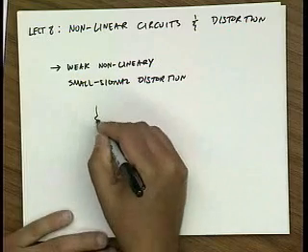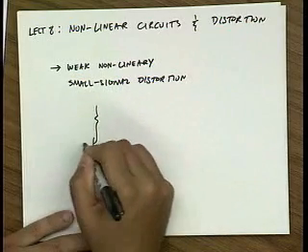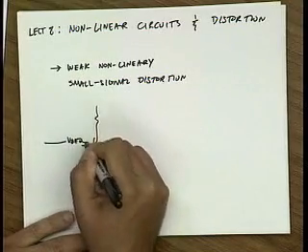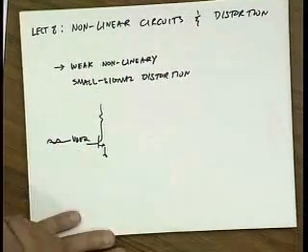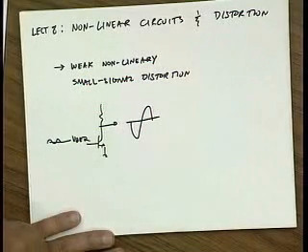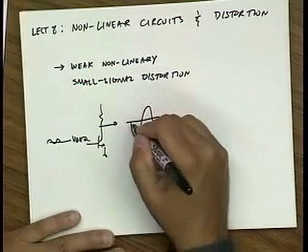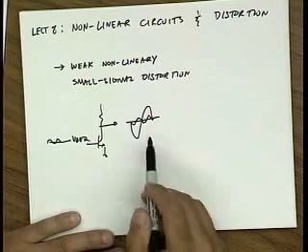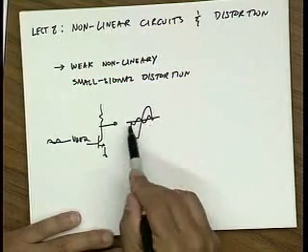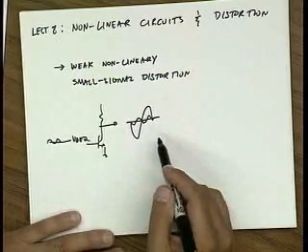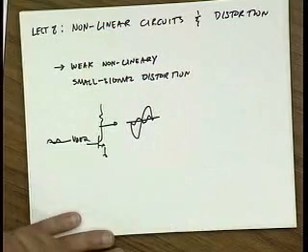So if we take a simple amplifier and bias it someplace, let's say VBEQ, we're still putting a relatively small signal on here, and then at the collector we get our output signal, and on top of it we're going to get this harmonic distortion. But the harmonic distortion is a relatively small part. Let's say it's a factor of at least 10 smaller than the main signal.